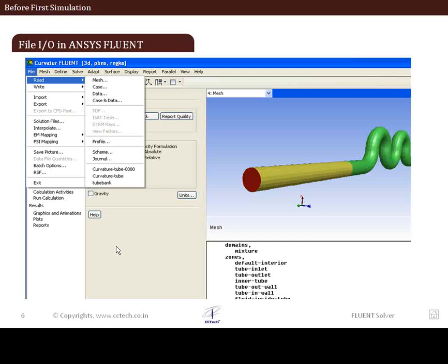We have already seen this some time ago in the previous lecture. What I had spoken earlier about was the different files that Fluent can handle and can read in or write. It can import or export. So the typical file that Fluent understands is the .msh file, which is the mesh file. We have the case file and data file. You can read in a case and data file together as well if they have the same names. And in addition, there are some other files located here. The very bottom corner that you see here, these are the history files that you had read in.